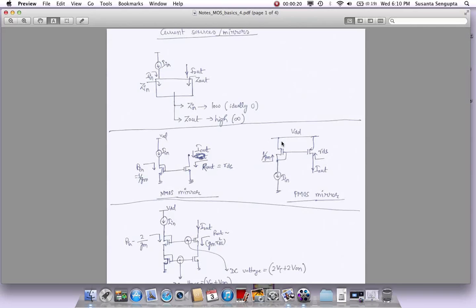You have seen me use this symbol, like this is the symbol of a current source. I've been using an ideal source, but in reality inside, when you make a chip, you have some circuits made up of MOS devices. They're called band gap circuits, which are used to generate voltage references as well as current references. So something like this could be generated there.